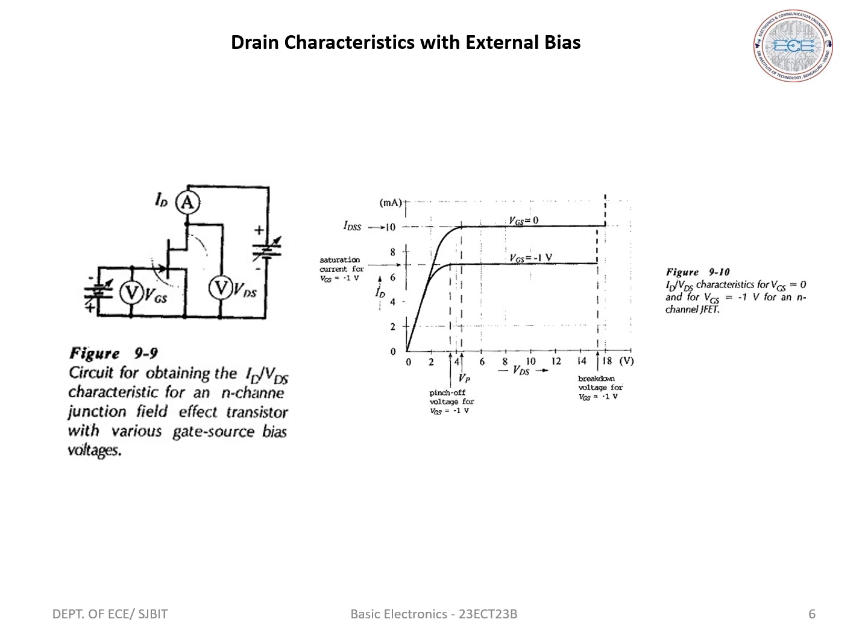When -1 volt VGS is applied, the gate channel junctions are reverse biased even when IG equals 0. When VDS is equal to 0, depletion regions are already penetrating to some depth into the channel. Because of this, a smaller voltage drop along the channel will increase the depletion regions to the point where they produce channel pinch off. When VGS equals -1 volt, pinch off is reached at a lower ID than when VGS equals 0, and VP equals 3.5 volts when VGS equals -1.